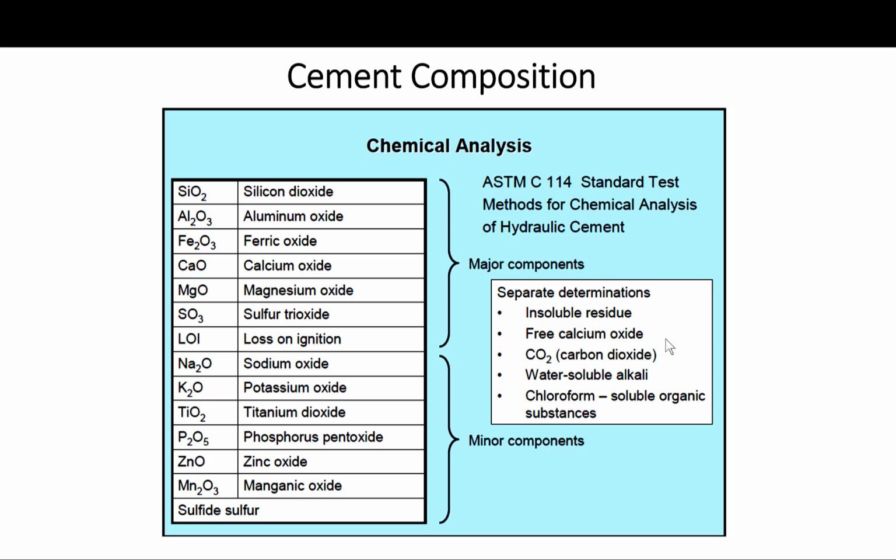However, an estimate of the relative rates of reactivity of cements with similar compound compositions cannot be made without, as I just mentioned, knowing the complete particle size distribution.